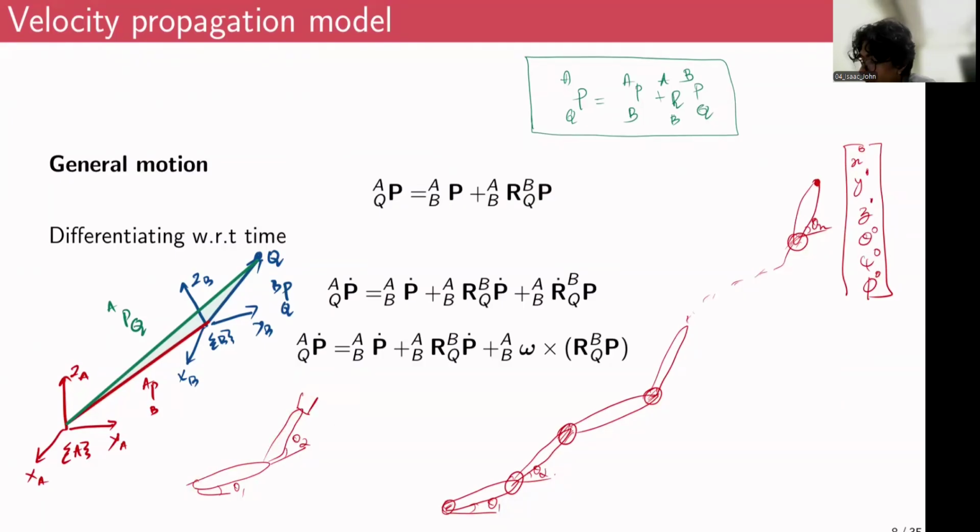If you keep theta 1 stationary and rotate theta 2, you will have another set of x dot y dot linear velocities. And if you actuate both theta 1 and theta 2, any linear combination would have an effect on the velocities at the end effector, in task space.